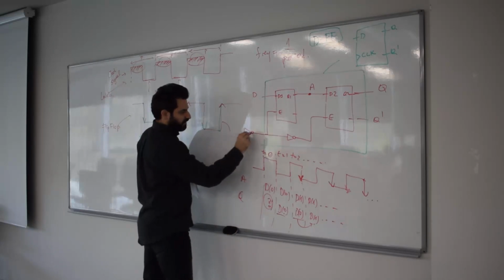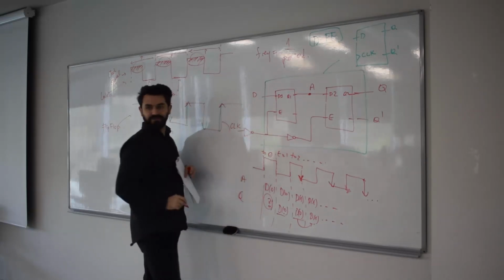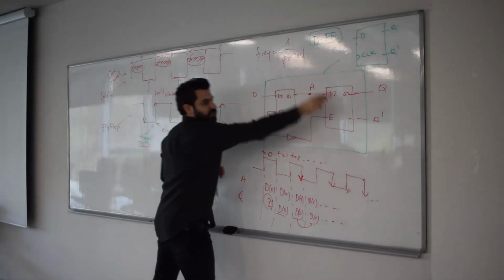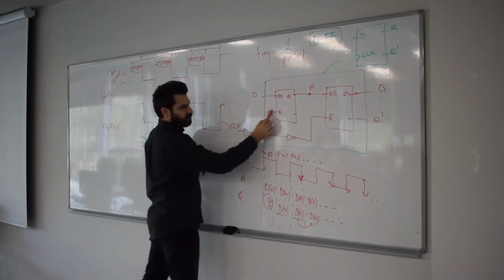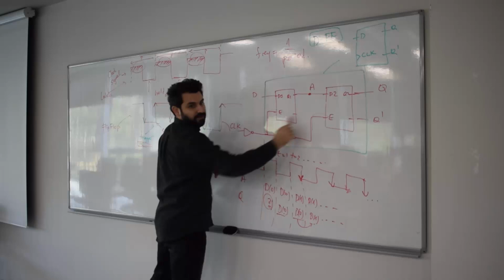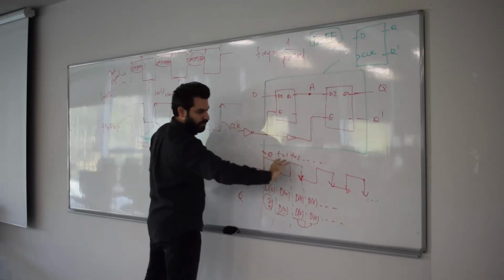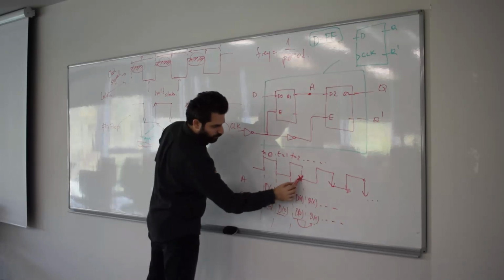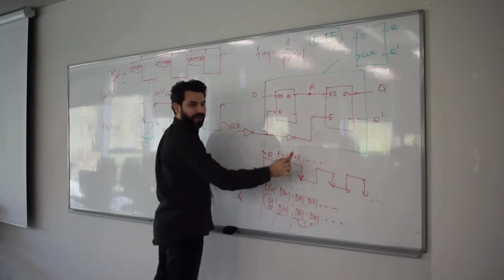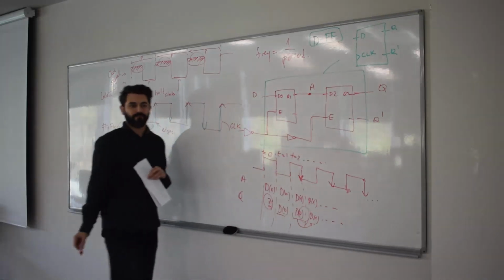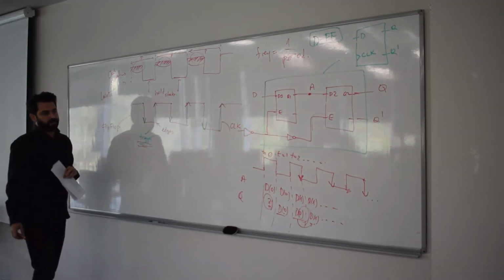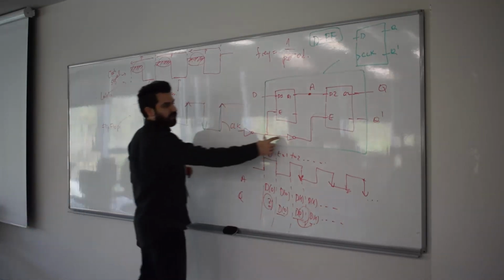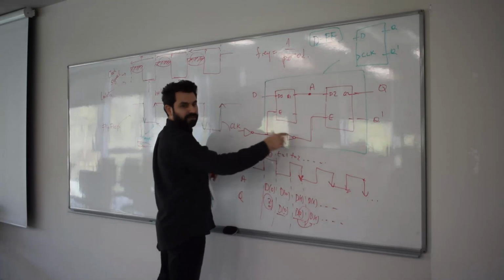So if you put a NOT gate here on the clock, you don't change the internal. This NOT gate would make this 0 and this 1, and so this is going to be turned upside down, so that therefore it's not going to be falling edge, it's going to be rising edge where the changes would happen. Or of course, as your friend said, if you're able to, you can eliminate that NOT gate, that would be the same.